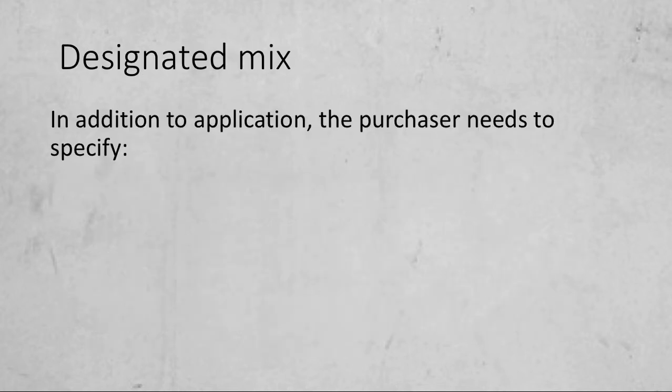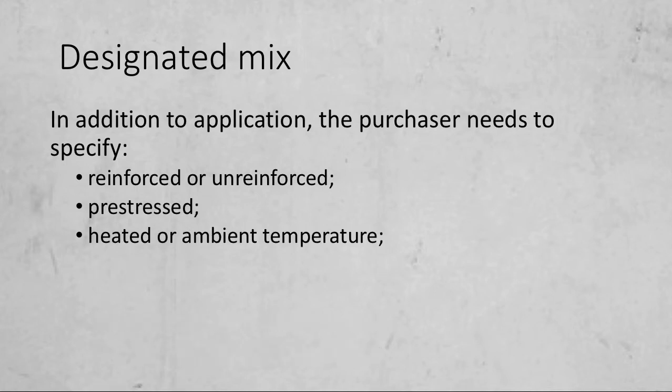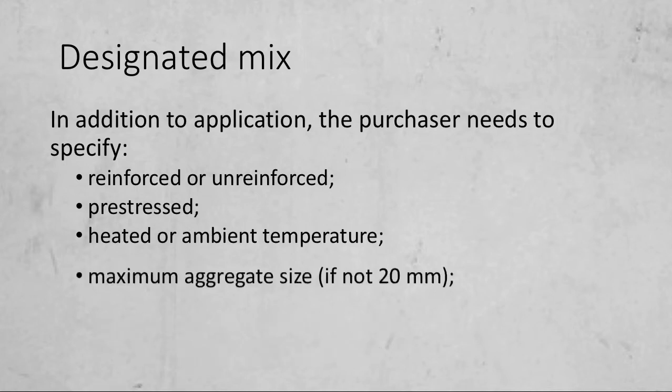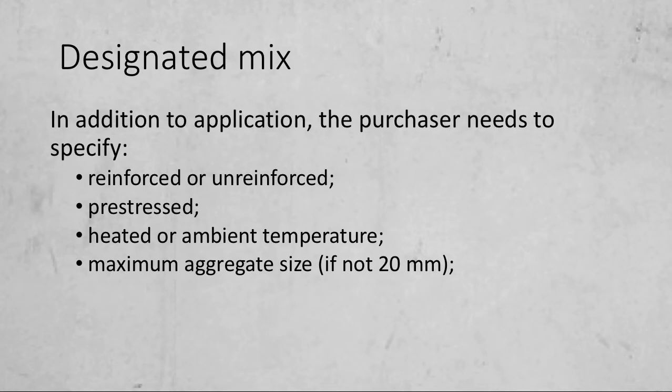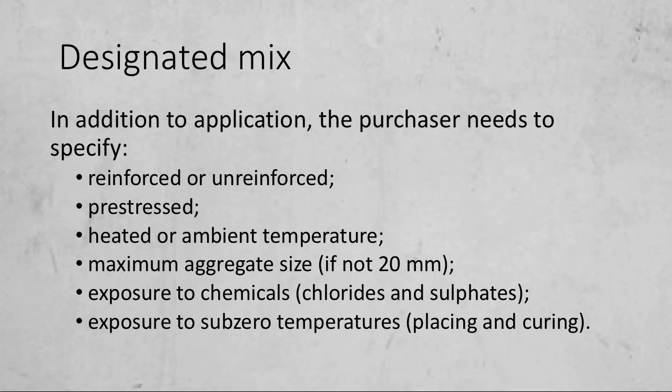Still with designated mix. In addition to application, the purchaser needs to specify whether it's going to be used on reinforced or unreinforced, pre-stressed, heated or ambient temperature, maximum aggregate size if not 20 millimeter, exposure to chemicals such as chlorides and sulfates, and exposure to sub-zero temperatures, which affects placing and curing.